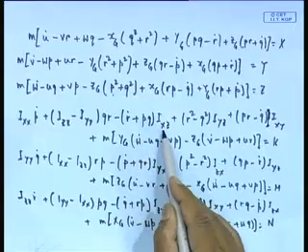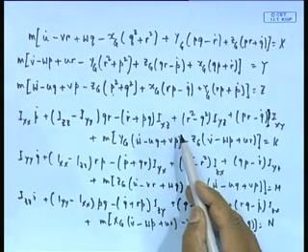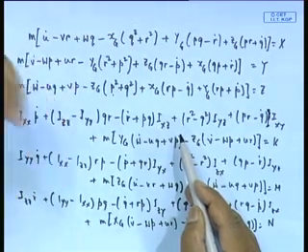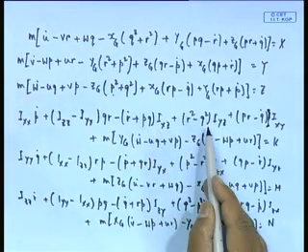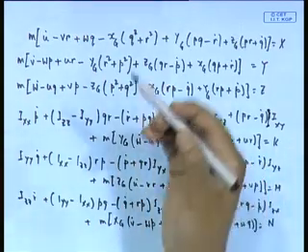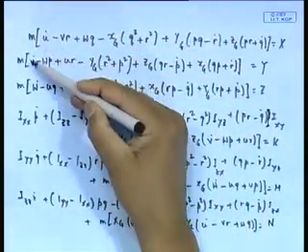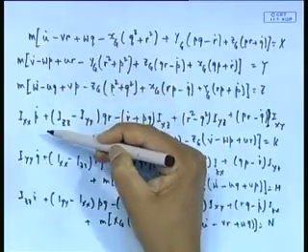Now, these x z, y z, etc. terms are coming because you are defining the coordinate at O, not at G. Had it been at G, then I would of course have only the principal moments of inertia, but because I am not at G, I am at O, I have this additional term coming. In a similar way this comes. The other thing I want to tell you is cyclicity. If you have written this one, you will find the first term u v w p q r, u v w p q r, v w u.